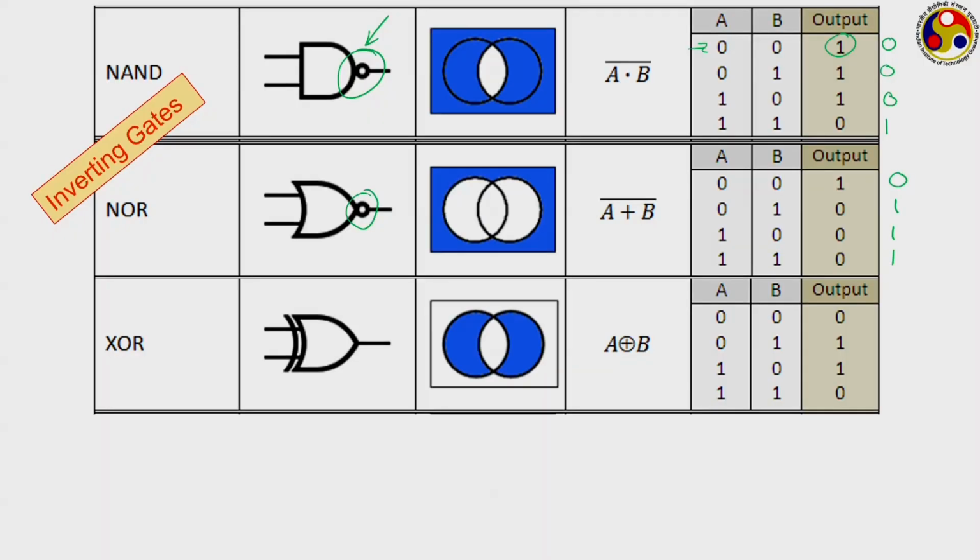And then we have a couple of exclusive gates. XOR is also called the exclusive OR. Here this curved line represents the exclusive portion. You can see there is an OR symbol and there is an exclusive symbol. This is quite interesting, the way it is represented mathematically. A plus B refers to OR, and now this plus symbol has been enclosed by a circle to represent XOR. In case of XOR, the output is quite interesting. When both the input signals are of the same kind, it is giving you a 0. When both the inputs are of differing kind, it is giving you 1.